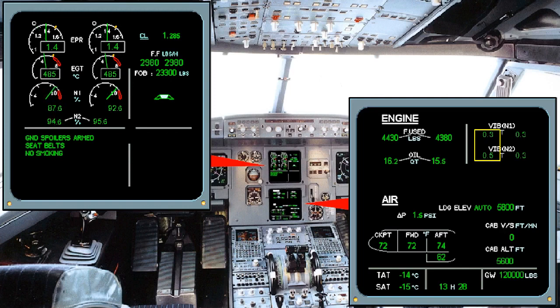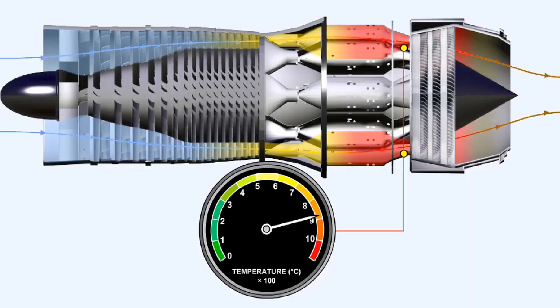An increase in the vibration level of the engine, which can generate noise, which may become audible in the cockpit, depending on whether the engines are wing-mounted or rear fuselage-mounted. And an increase in the exhaust gas temperature, otherwise known as EGT. This latter effect, the increase in exhaust gas temperature, is caused by the fact that there is less air going to the combustion chambers. Hence, there is less air to cool the products of combustion, the exhaust gases.